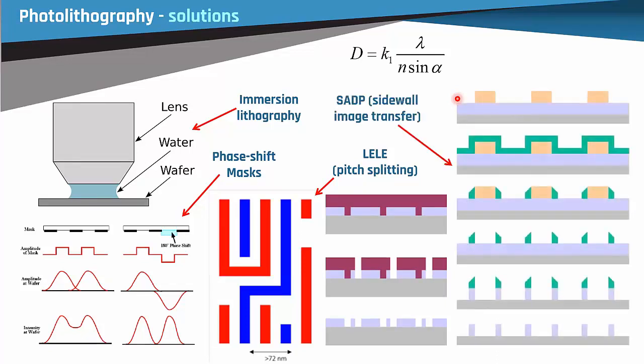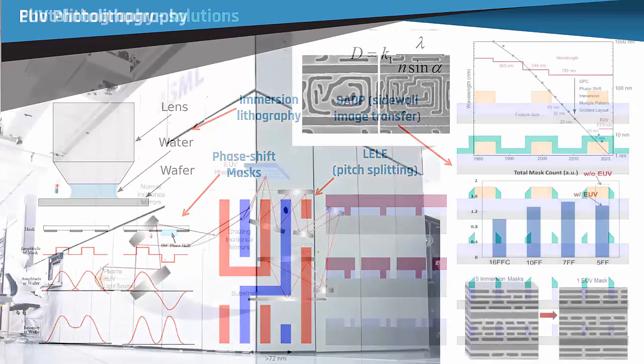But what's really brought us to be able to print up to 7 nanometers with 193 nanometer laser, which is completely ridiculous, right? Is what we call self-aligned double or quadruple patterning. And again, we'll be showing how this works next week. So these are tricks that have brought 193 nanometer laser up till today.